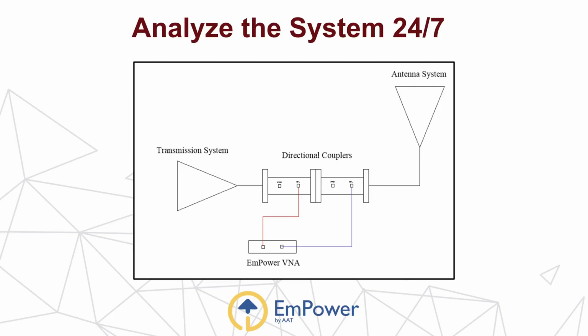An example of how we terminate that is the transmission system of the transmitter, coax, and antenna. At the beginning of that transmission system, we put directional couplers, and that allows us to couple the test equipment via the directional couplers through ports into the transmission system, allowing us to analyze the system while the system is functioning. On the air, we can complete analysis.